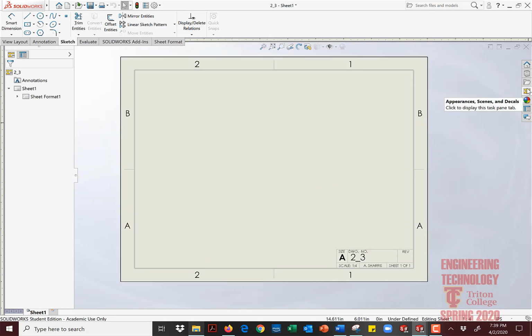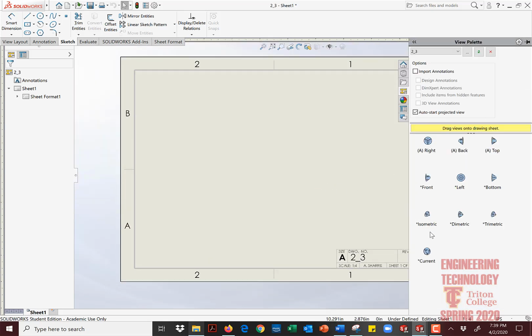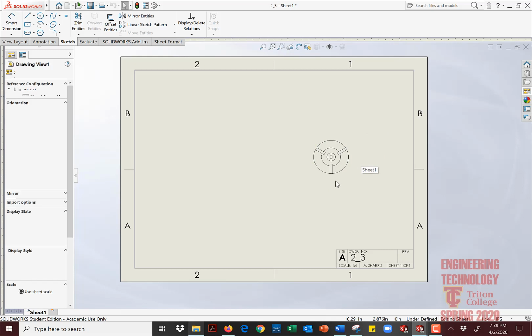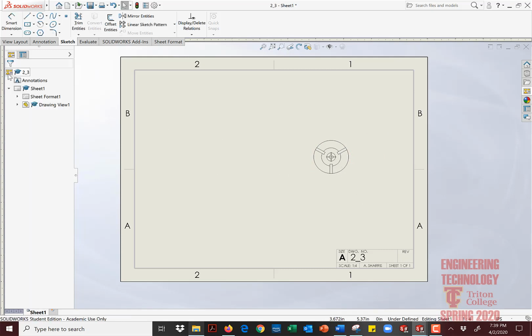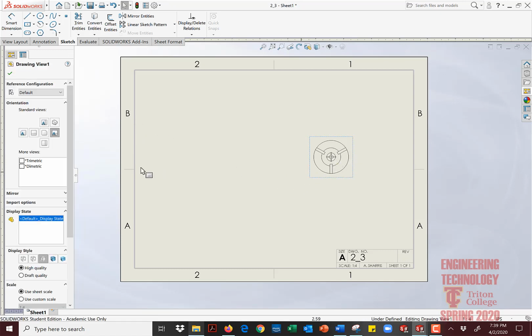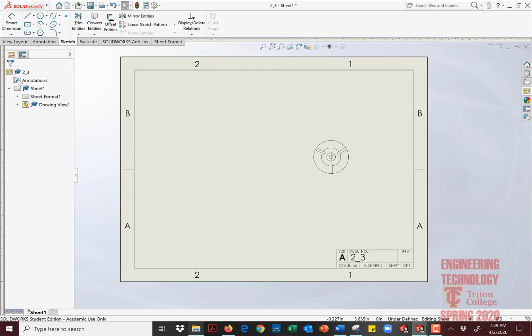When you open the title block, the border, you'll have the option to bring in your views. The only view I'd like you to bring in is the right side view, but it needs to be put in the correct spot, the right side. Okay? Just bring that one view in. Now the scale's pretty tiny, so the next thing you want to do is change the scale.